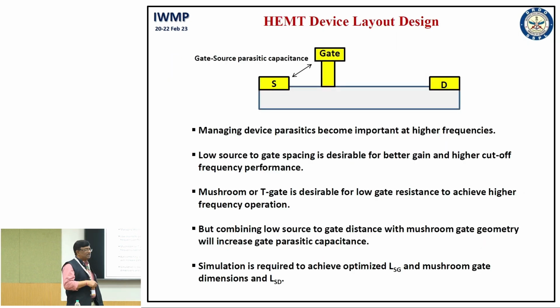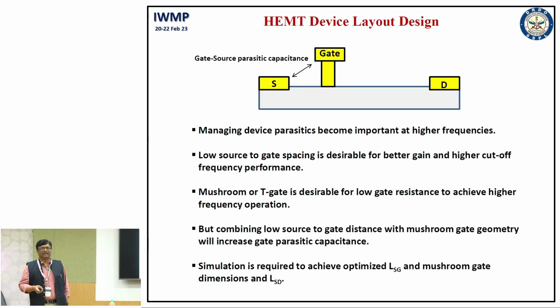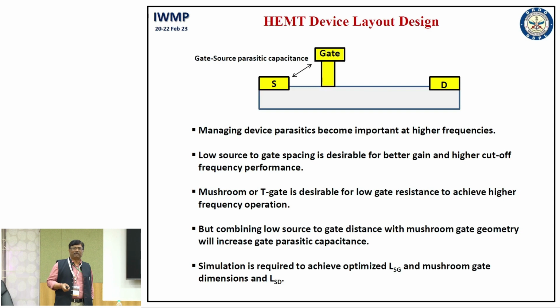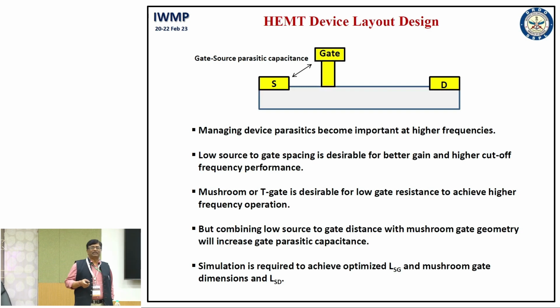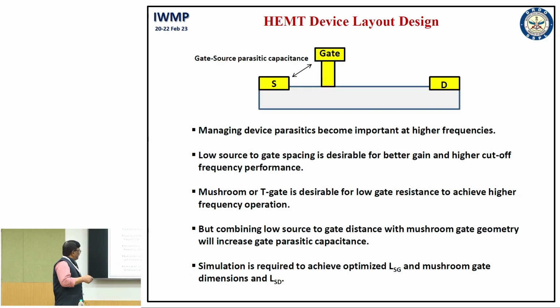And mushroom gate is normally used. Mushroom gate is used to have a smaller footprint that defines the high frequency performance, and the broader head to reduce the gate resistance. Therefore, simulation is very important. So, TCAD simulation is extensively used, mainly Atlas from Silvaco is used to simulate the device performance, and then actual experimentation is carried out.